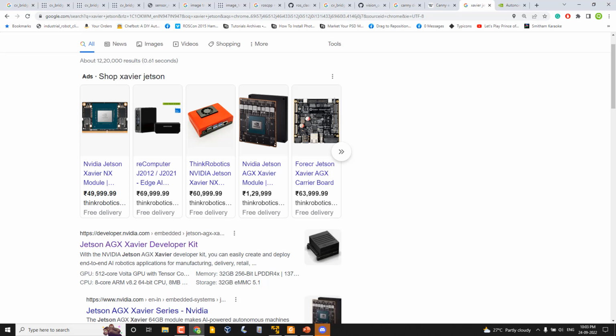If you're working with the Jetson Nano with 4 GB, and you run the simple navigation, it will take 2 GB or 2.2 GB of RAM, and also 1/4 of the CPU. And when you run the people detection algorithm, then it's game over. It can't run.